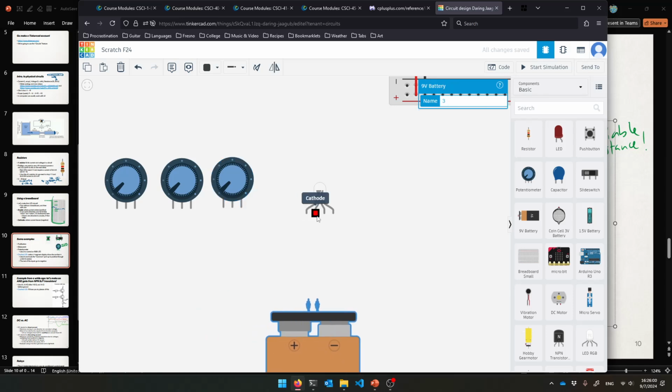Everything else is going to come from positive. The idea is we feed positive into each of these potentiometers and spit them out into the red part, the blue part, and the green part, and that will correspond to how much red, blue, and green you want emitted. So you can turn up the blue, turn up the red, and make purple or something.